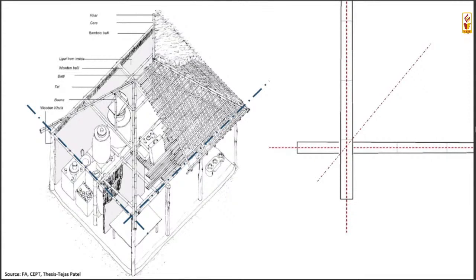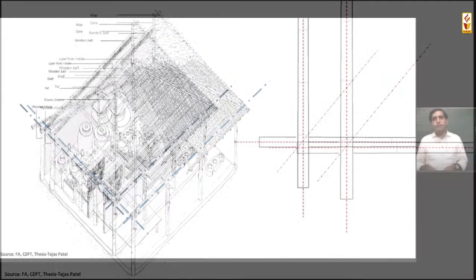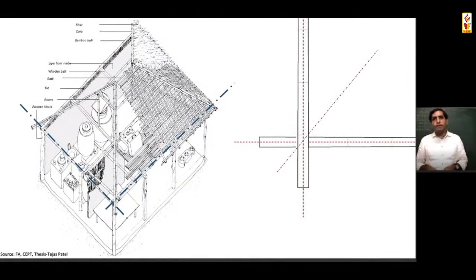The moment one bamboo is up and one is down, that affects your slope. If you are making a roof, you'll find that the slope in this direction and the slope in this direction are not going to match, because at that point you have got a level difference. So what compensatory action will you take in order to level that? That is a detailing challenge. There are ways to do it, we can resolve it, but I just wanted to make the difference between steel, timber, and bamboo once you start looking at the corner conditions of detailing. Go next.